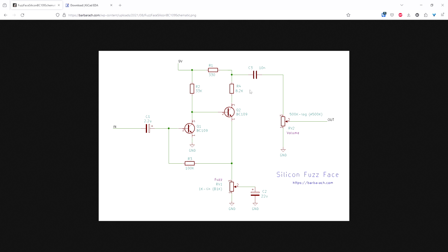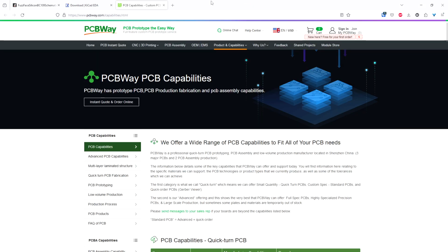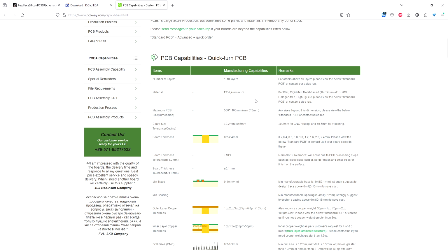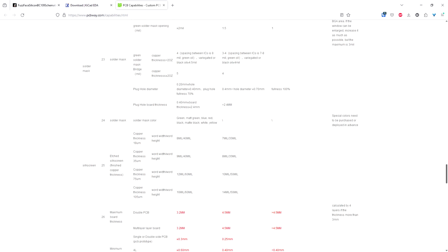Before we plunge into this, I hate working from scratch. I usually either copy paste my previous project and then work with that, or I'm leaning towards templates. The reason for this is every fab house has its own set of capabilities: the number of layers, the materials, maximum dimensions, maximum tolerances, etc. So if you look at PCB, there's quite a lot there.